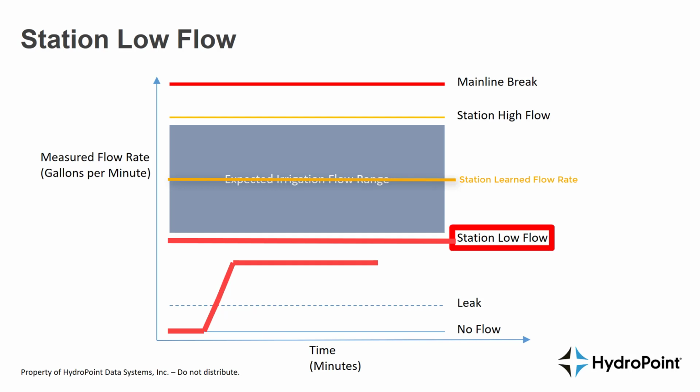However, the station low flow alert is not service affecting, meaning even though the alert is raised, the irrigation will continue through the entire scheduled runtime.